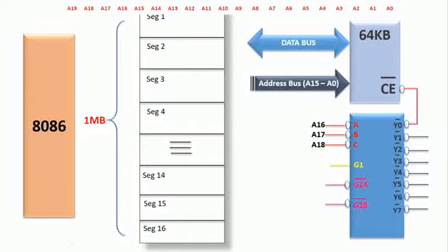Okay. So here, how many address lines have we used till now? Totally 19 address lines we used, because A0 to A15 are directly connected to the address lines of the memory device, and how many are left? We are left with the 4. Out of these 4 lines, 3 lines are used as input lines to the address decoder. Those are nothing but A16, A17, A18.